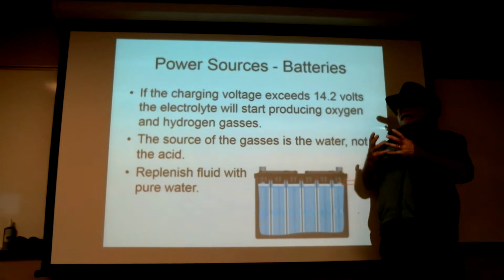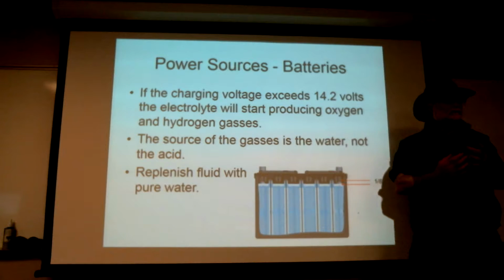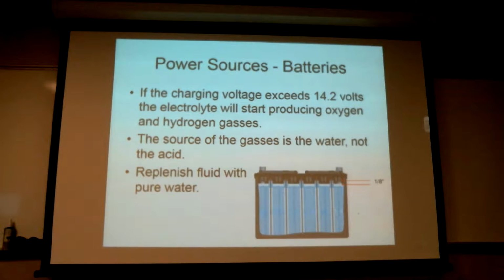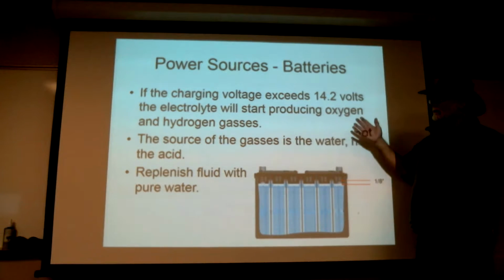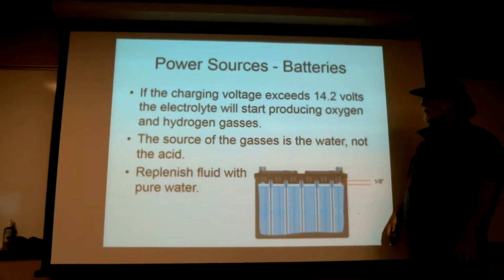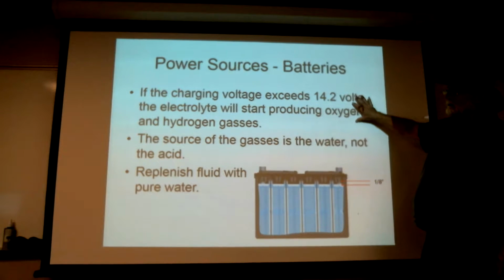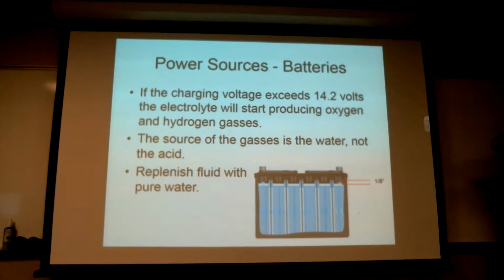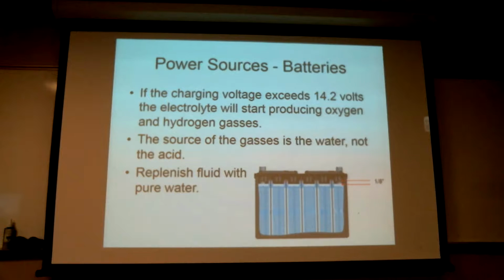And that's true. If I take a soda and I pour it out on the table and come back the next day, all the water will be gone and I'll have a sticky mess here. Okay. The sugar didn't evaporate. It's a pretty nasty sticky mess, covered with ants and stuff, and cockroaches and other icky stuff. Okay, same thing would be true here, only the acid would also have eaten a hole in the table. So batteries that are overcharged or charged at too high a rate. Well, now wait a minute. How do I get it to charge above 14.2 volts?